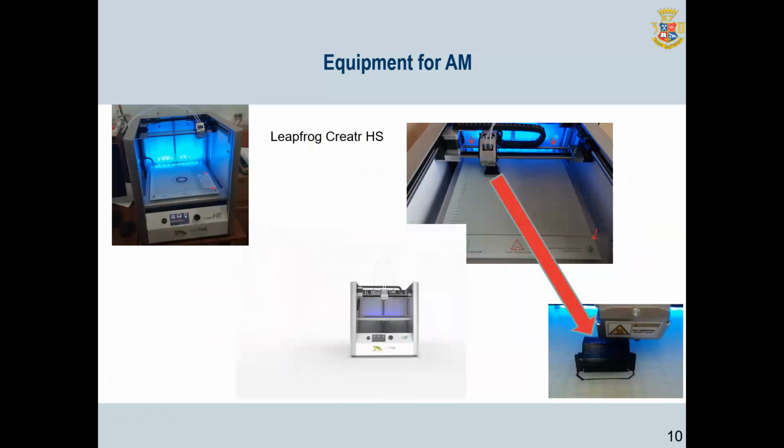Thermoplastics such as ABS or PLA plastics are used as 3D printing material. Consumer 3D printers are well suited for printing 3D models with simple geometry where increased accuracy is not required and the presence of visible layers of printing is not critical. Let's watch this video illustrating the 3D printing process with our 3D printer Leapfrog Creator as an example.